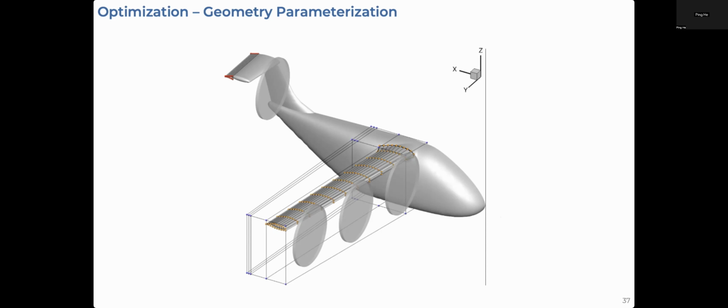Our objective value, which is the cruise thrust, oscillates at the beginning and then stabilizes through the optimization, and the overall aggregated trim residual decreases below the required tolerance. And for the failure of the wing and the tail, we don't exceed our value of 0.67, which is a failure of 1 with a safety factor of 1.5. So gradient-based aerostructural optimization helps us design a feasible and optimal aircraft.